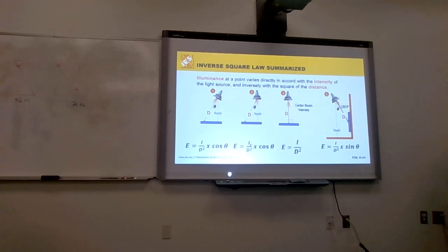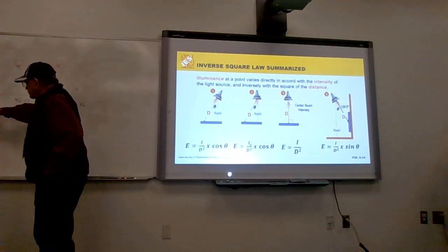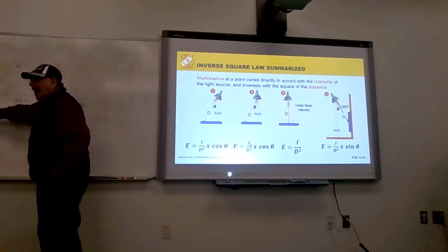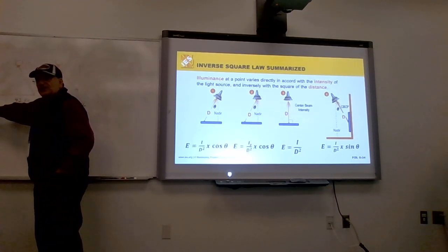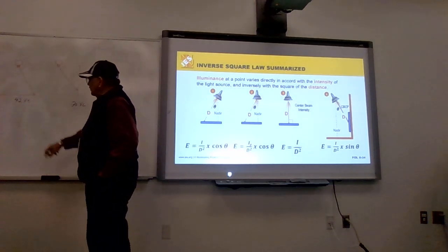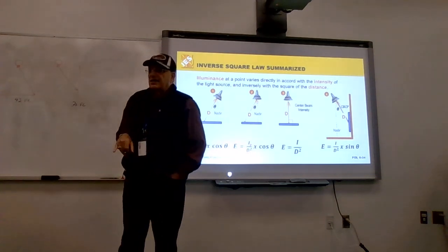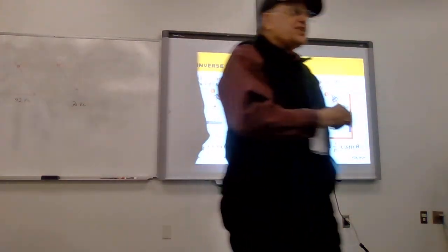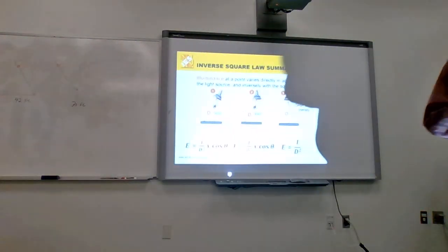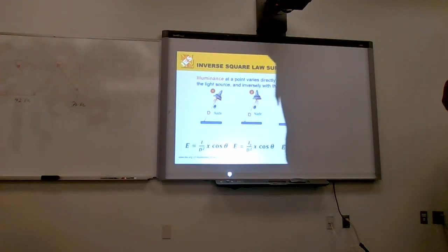And there you see the variation. We just did a calculation expecting the most intense light would be directly underneath the light source. As we move away from the light source, the foot candle levels drop. And if we start to introduce a severe angle on a vertical surface, the foot candle levels drop even more. We kept in this example the distance the same, 10 feet. I did that deliberately. Okay? I also kept the candle power deliberately the same in this example.